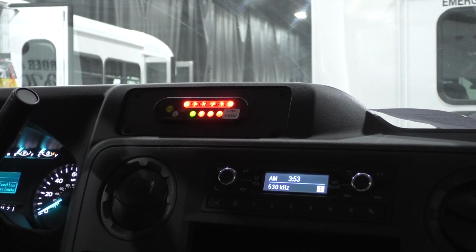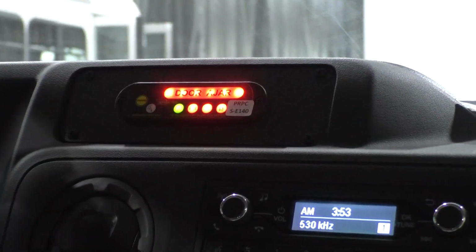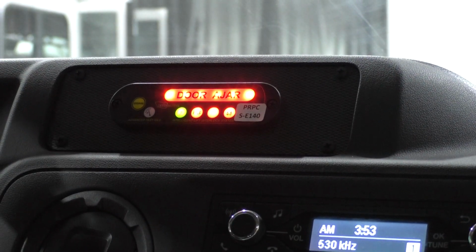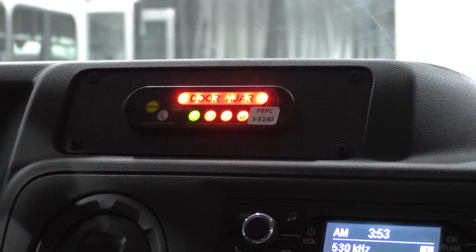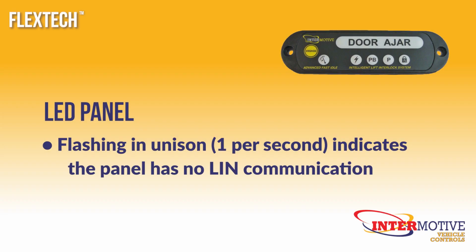As the last module in the LIN harnessing, if the gateway panel is operating and the LED lights are responding to commands, then you know everything is good. If the gateway panel LEDs are flashing in unison, about 1 per second, that indicates the panel is powered, but it has no LIN communication.